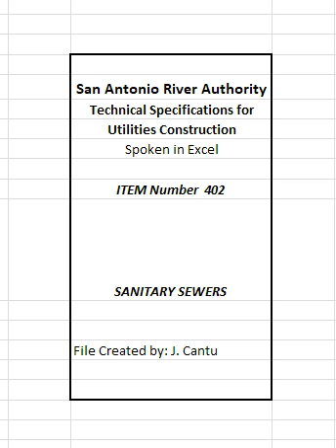When bell and spigot pipe is used, the position of the pipe bells shall be determined by measurement, and cross excavation just adequate to admit the pipe bells without bearing shall be cut. It is specifically provided, however, that if rock occurs in boulder ledge or coarse gravel formations at the bearing level, it shall be removed to a depth of not less than 6 inches below the lowest bearing level of the pipe and replaced with approved select bedding material in conformance with item 404.2a, Bedding, after which fine grade and excavation for bells shall be done in the manner described above.